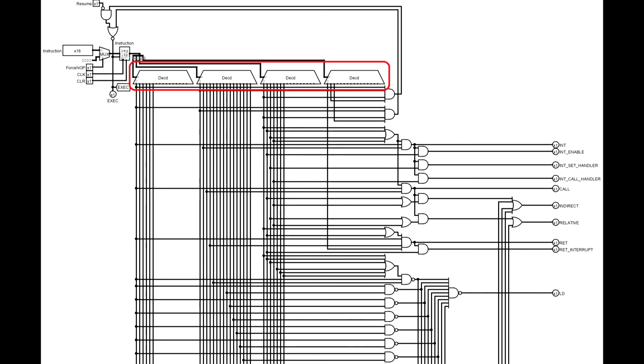At the top of this circuit, I have 4 decoders, each of which decodes 4 bits of the instruction that is loaded into the instruction register. The 2 decoders on the left work on the opcode, while the other 2 work on the operands, which often contain extra data for the loaded instruction. Other times, the operands hold the address of the register in the register file where the data is to be used, read from, or stored to.